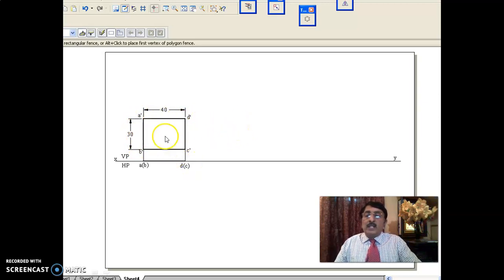Now you see in this position, as you see 30/40, you have the top view and front view. This distance is how much? 40. Once you start pulling it, when DC is pulled, the top view 40 will remain the same. That is why the first stage top view and second stage top view will remain the same.